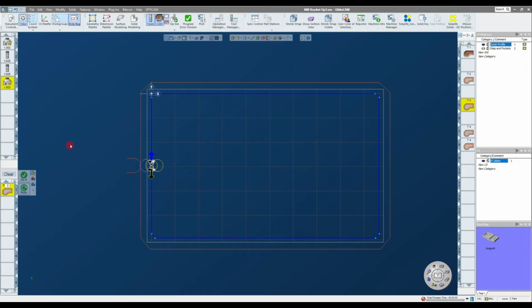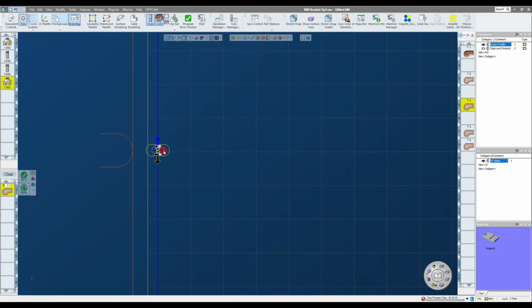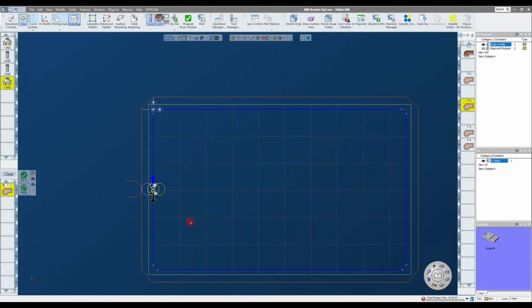So the way the markers work is, as I said, you have the tool on the left side of the geometry, the center on center of the geometry, or on the right side of the geometry, and you can pick the direction you want your cutter to proceed. So left side and proceeding in this direction is climb milling around this part.